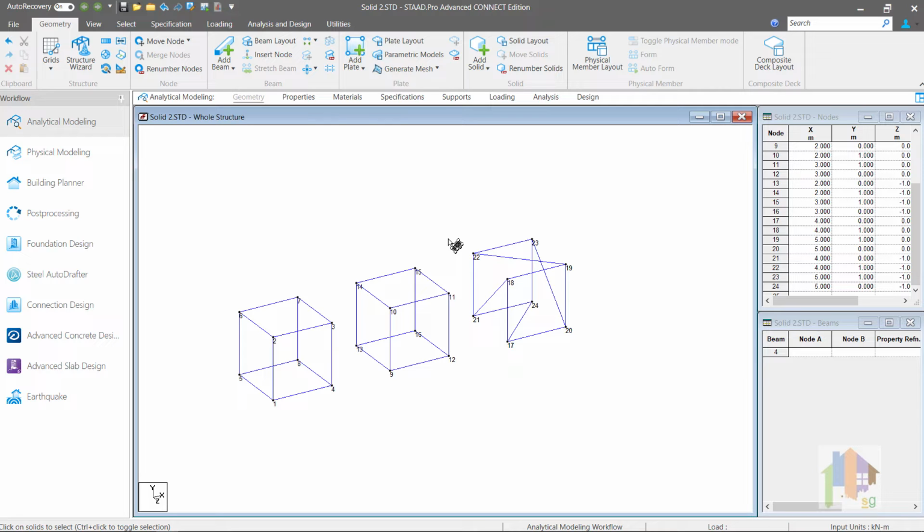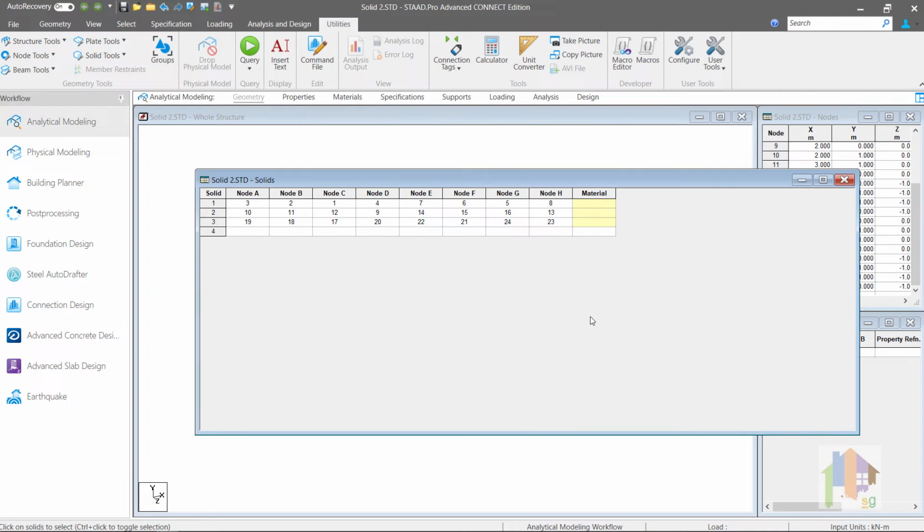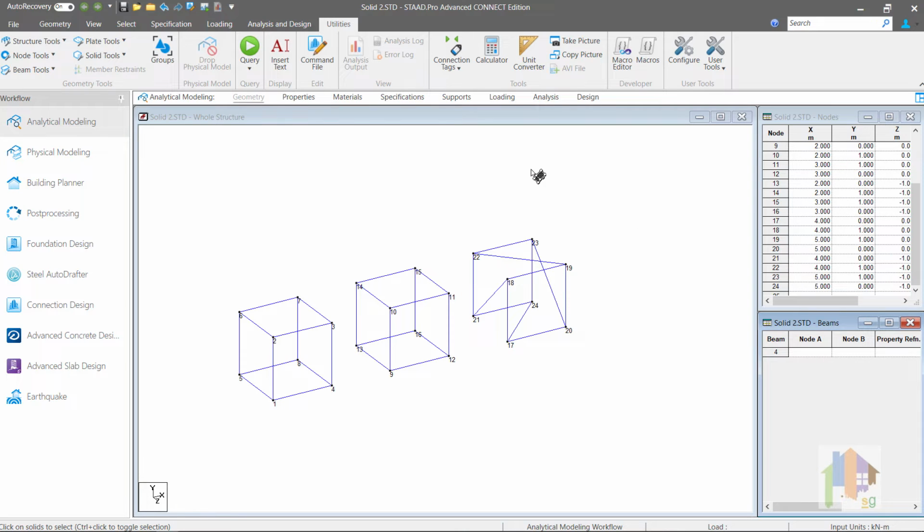From these two examples, you can easily understand how hard it is to generate a solid element. There are 8 nodes and all those must be selected properly following correct order, else the generated solid will provide incorrect analysis result. It is also very hard to identify the problems from the GUI. And imagine that for a dam or foundation model, you have to generate thousands of such solid elements. Yes, it is very hard and also prone to error.